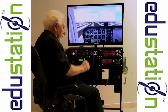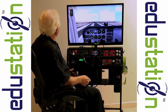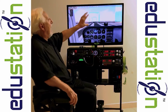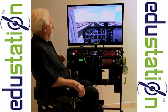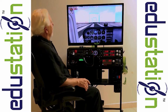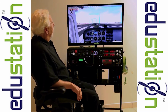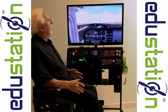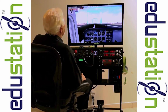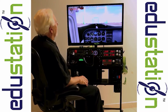And so when we load the mission, you're going to hear a verbal tutorial telling us how to execute the mission. Then advance the throttle all the way forward. So we're asked to advance the throttle all the way forward. The airplane has a left turning tendency. To stay on the runway center line, gently. So this airplane has what's called a left turning tendency because of the propeller spinning. And if the plane moves to the left, you use a little bit of right rudder, and that will keep you on the center line.